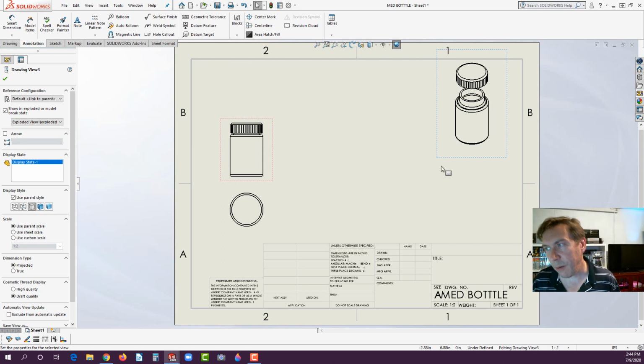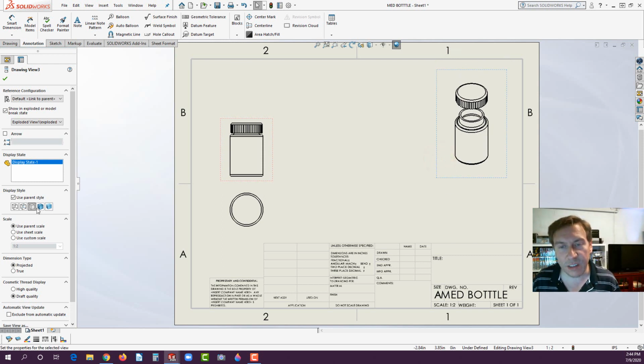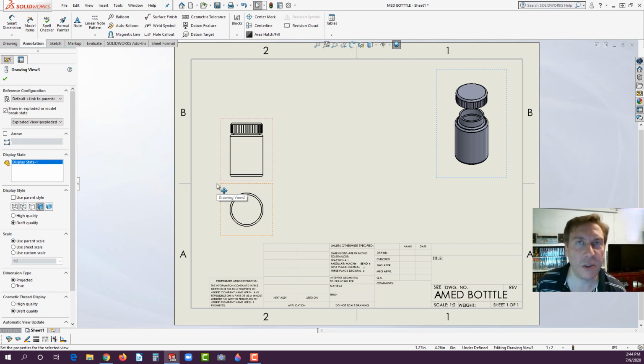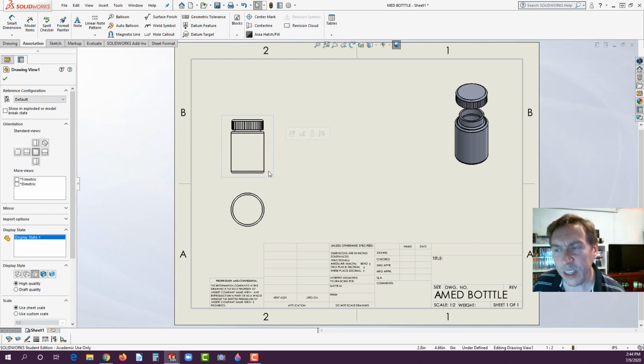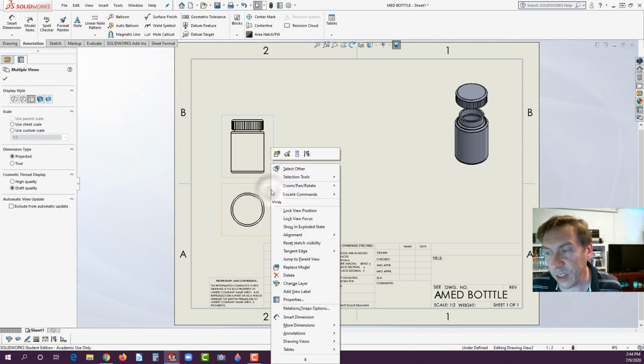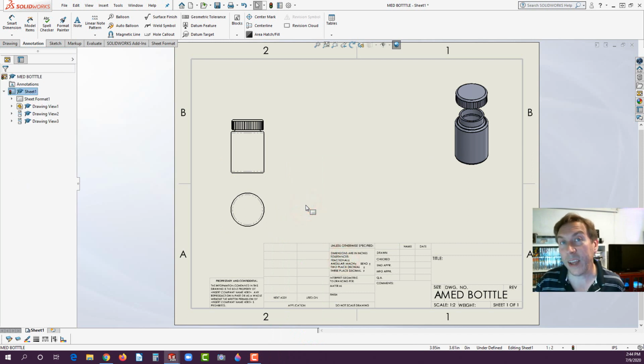And anyhow, let's drag this down. You could shade this if you click on the shade tool. I don't really care for my students if you shade it or not. It doesn't really matter to me. But these additional views I don't want shaded. Now these views here, if you control select, you can right click, tangent edge, and tangent edge with font. I want you to put that in there. Those are 5 points apiece, so if you miss those, 5 points off. And those are quite common. Some people say, oh, you're being too demanding. And I feel, though, it's very important that you know how to use all these tools.